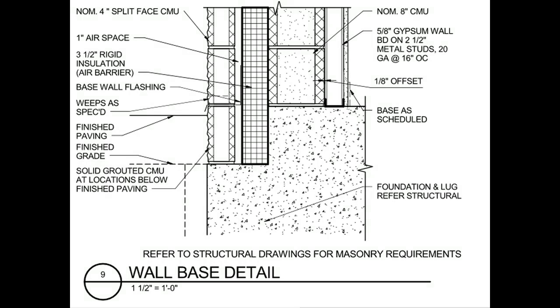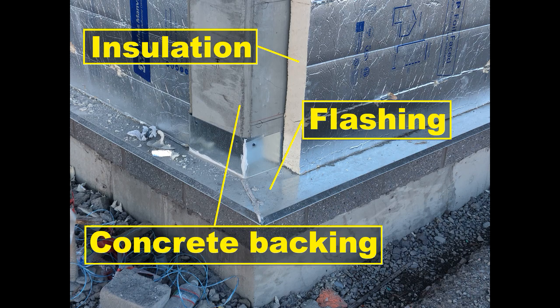Insulation. Insulate cavity walls, and non-composite masonry walls, where shown, by installing board-type insulation on the cavity side of the inner wythe. Apply board-type insulation directly to the masonry or through wall flashing with adhesive. Neatly fit insulation between obstructions without impaling insulation on ties or anchors.